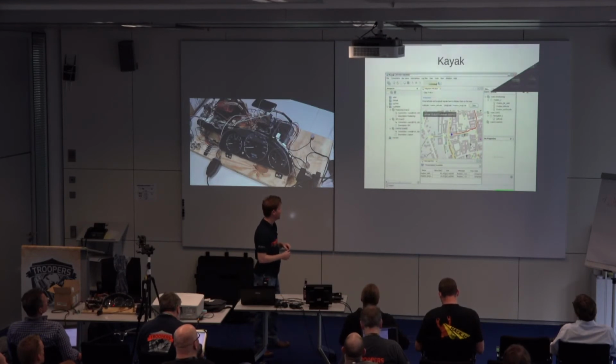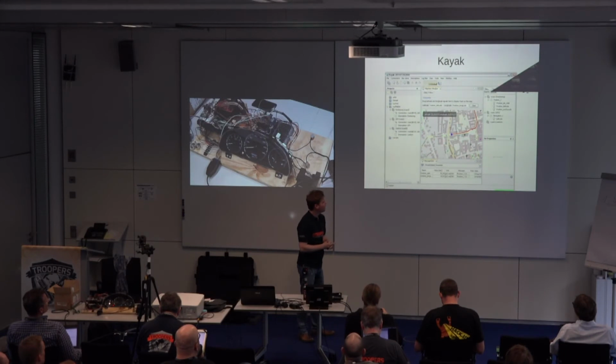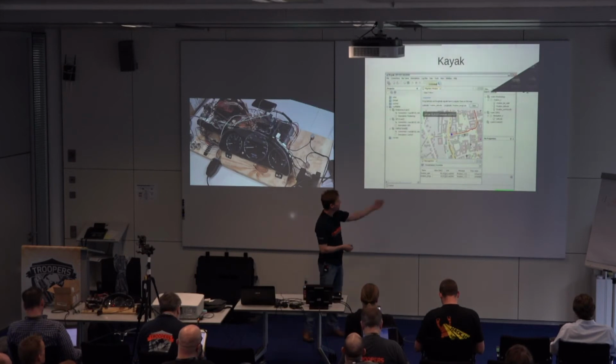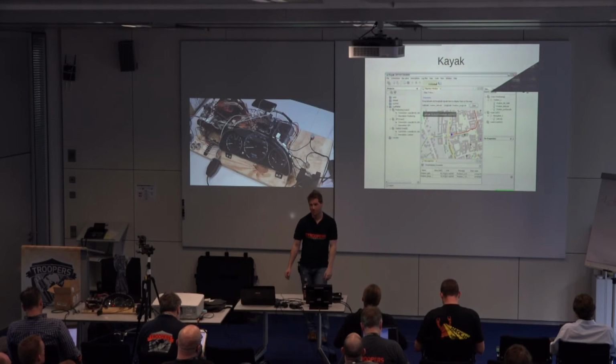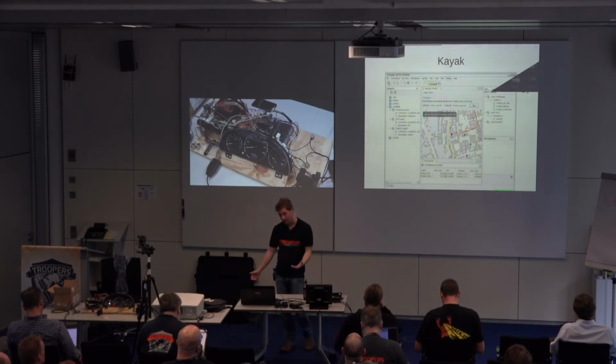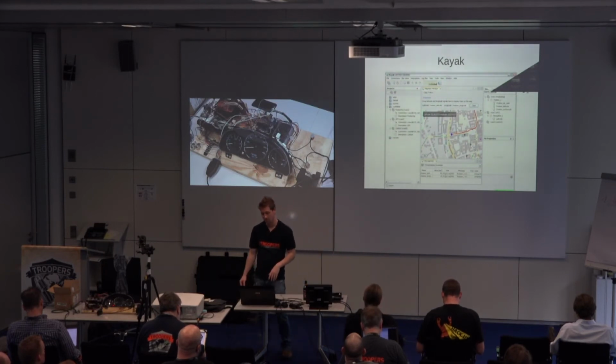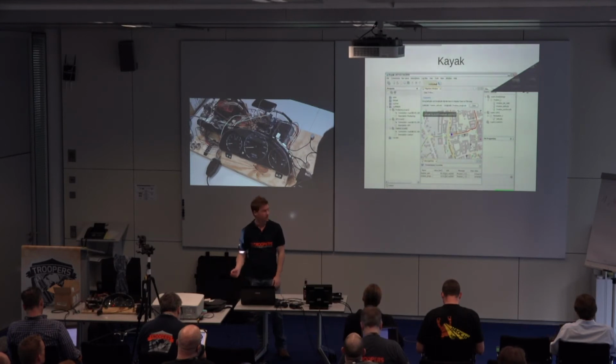And this particular screenshot I kind of like because when you do figure out a piece of CAN, you know, this byte offset is running, in this case, GPS stuff, you can mark them. This is latitude, this is longitude. It will use OpenStreetMap. So if you record it in a vehicle driving that has latitude and longitude going on CAN bus, you can then slap them over here and then watch it on a map or whatever.